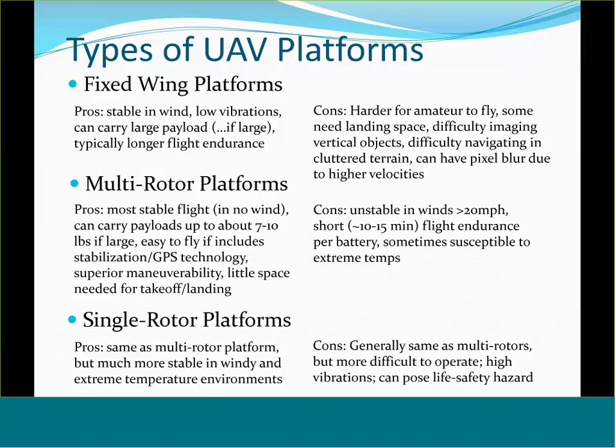Some of the downsides, though, is that they can be a little more difficult to fly and operate, and they tend to have more vibrations than multi-rotor platforms. And if you start dealing with some of the larger single rotor platforms, they can pose a life safety hazard, and so you want to be sure not to operate them over large crowds, where if it's going to come down, they may actually really hurt somebody.